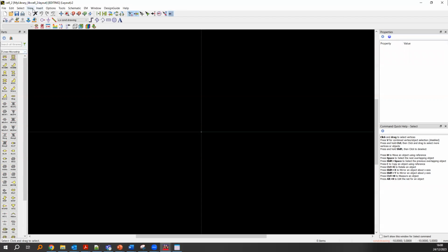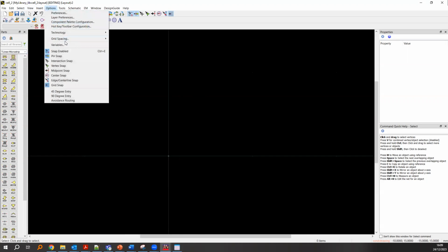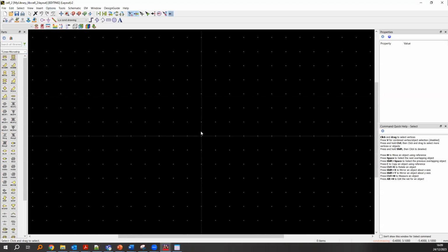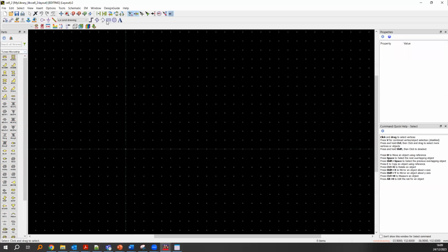Of course, if you're working with a more complex design, you can import these from a PCB or an IC design software, which is what most designers tend to use. Before we do anything on the layout window, we are going to choose the grid spacing that we're working with. So everything in the layout will snap to grid. We're using millimeters, so a resolution of about 0.1 millimeter is going to be appropriate and also not too fine, which makes our drawing easier.